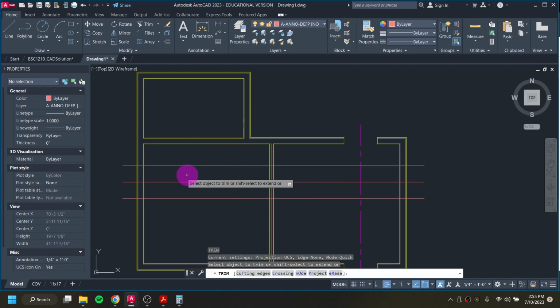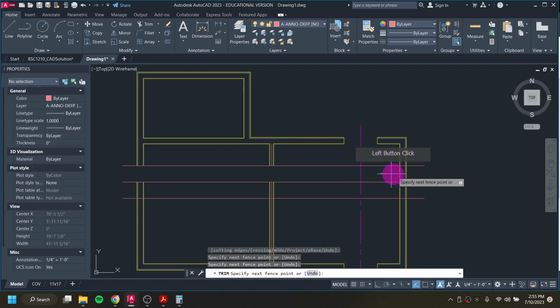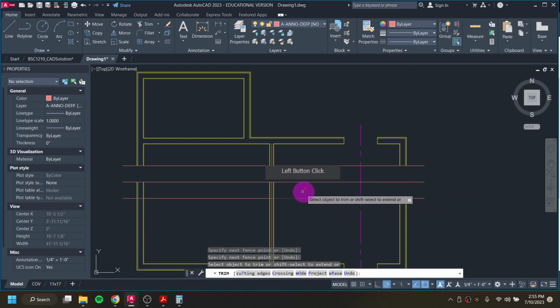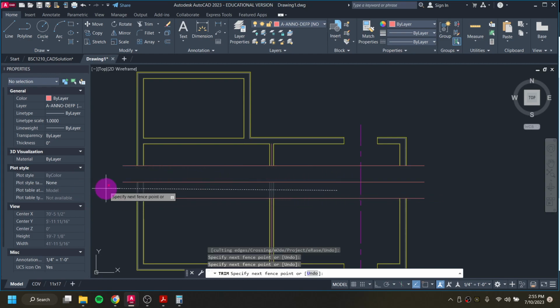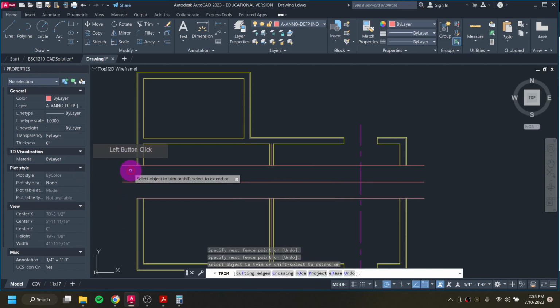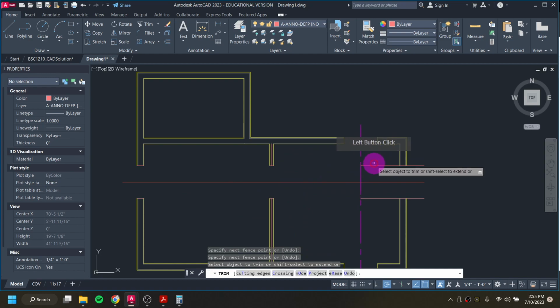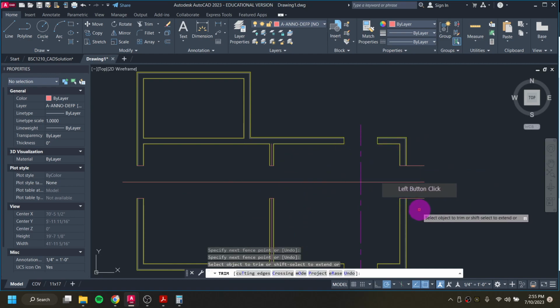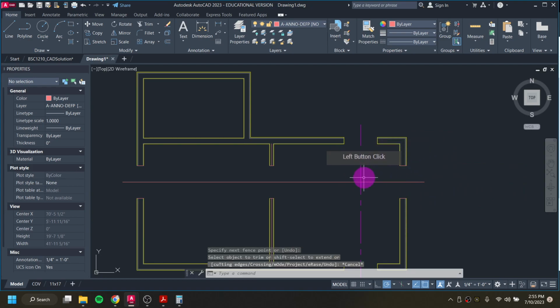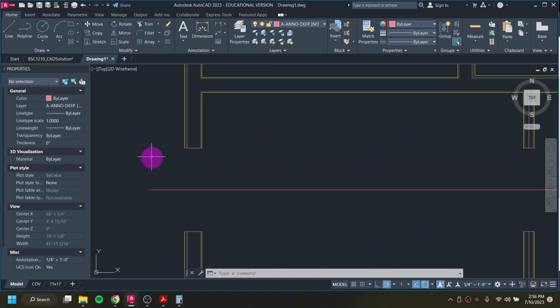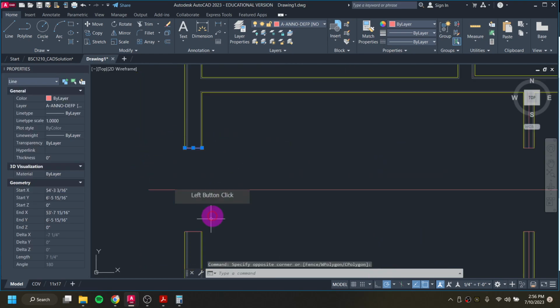So that's TR, enter. I'm going to trim just from out here straight through. Same thing over here. I have to just kind of stop because I don't want to trim that line I put there. Click in the abyss and then just move my cursor straight through all the things I want to cut. Get rid of that, get rid of that, this. So I'm just kind of going through and cleaning up all this line work. I could have also just, again, redrawn this, but I don't know. I feel like maybe I'm saving time, maybe I'm not.